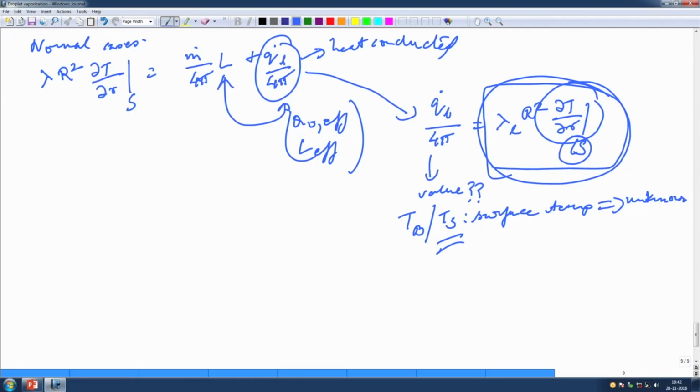Now, before we go on, we can establish a few quantities over here which will help us. Some of the quantities you already knew. Now, for unitary Lewis number, that is Le equal to 1, the Lewis number means your thermal diffusivity and your mass diffusivity are of the same value, so it is basically rho D equal to lambda by Cp.